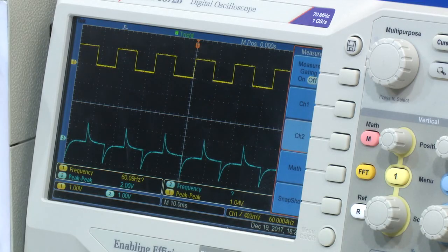Here the case is different. In case of the integrator, when we were applying about 5 volts, we were observing 2.4 volts. Here we are applying an input signal of 1 volt, and we are observing the output as 2 volts. But you do not have to only measure the output, you also have to comment on the shape of the waveform, and the shape of the wave is nothing but a spike.